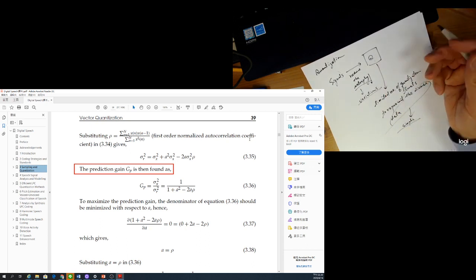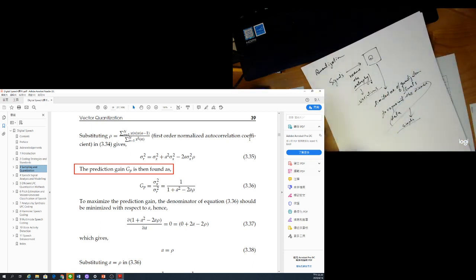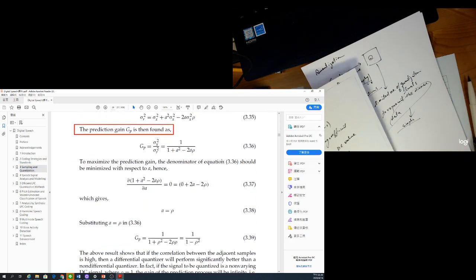You can see what we talked about previously, like the adaptive quantizer, which divides by the dynamic range or standard deviation to make the variation smaller, so we can design a unity gain quantizer and something like that. It looks like we are trying to make your signal more uniform, so the data is easier to quantize. Okay, before I go to vector quantization, I'll use Mandarin to repeat a little of what I said before.